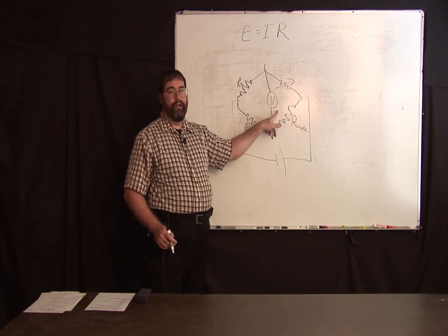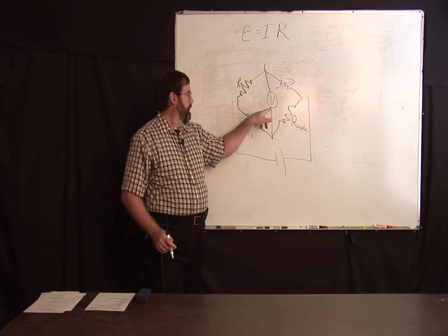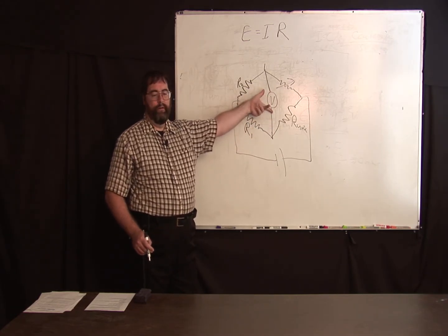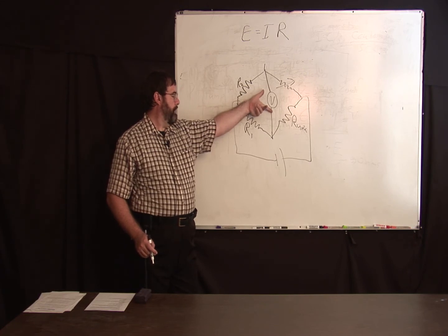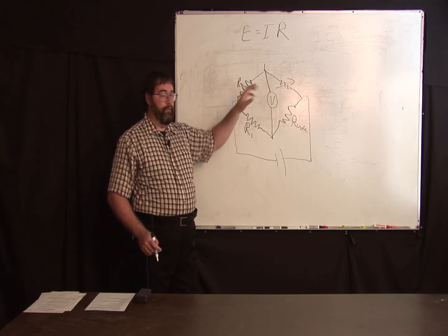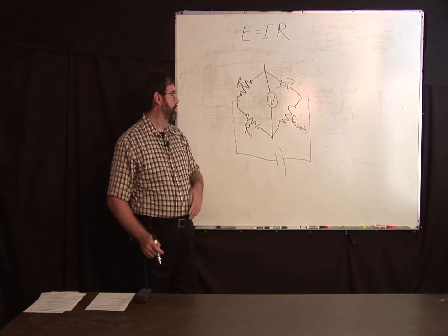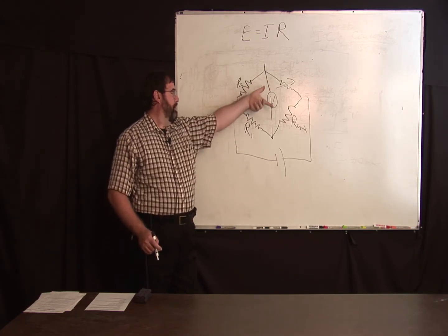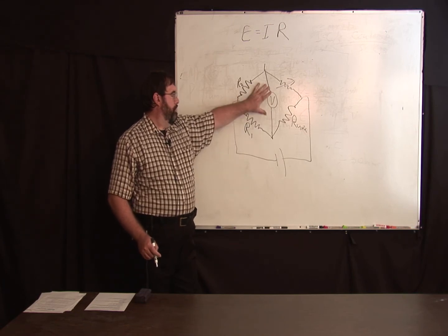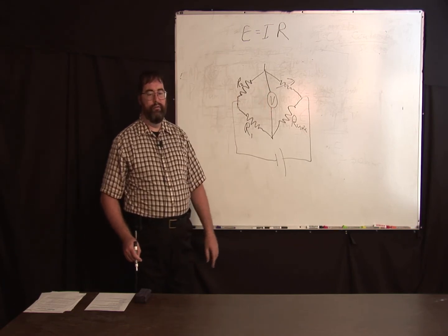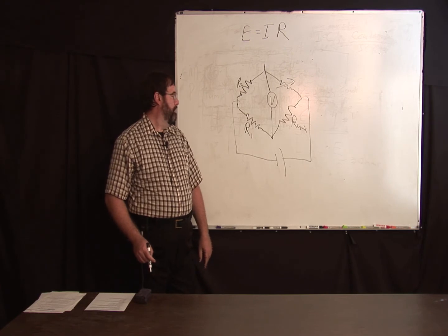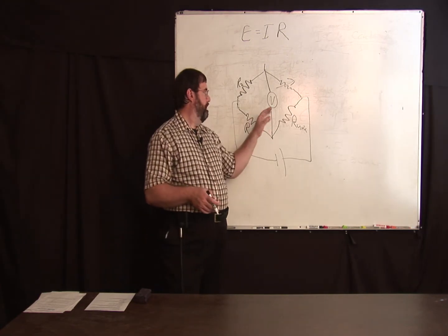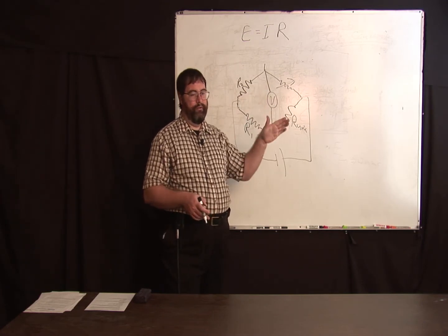This doesn't even have to be calibrated, it just has to work. This voltmeter, for instance, you could just switch the leads on the voltmeter. If the thing doesn't move when you flip it around, that means the bridge is balanced, because maybe your zero's off on your voltmeter, but if you flip the leads, it's going to move the needle.